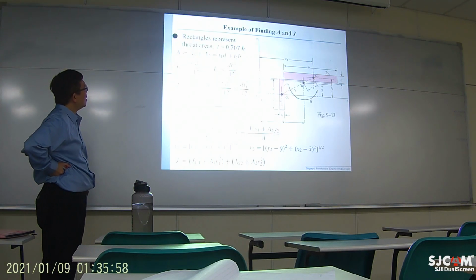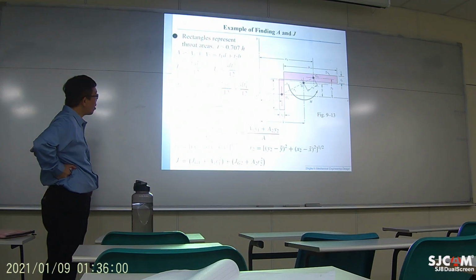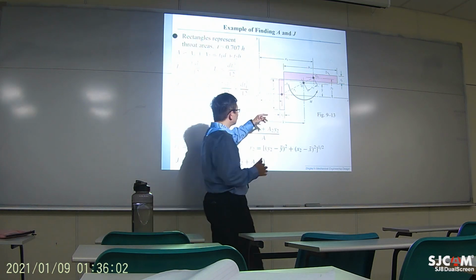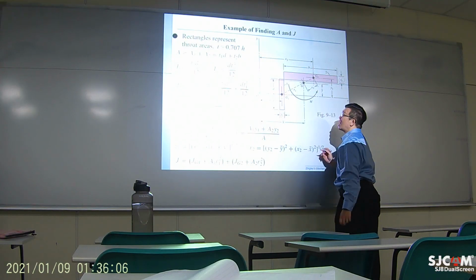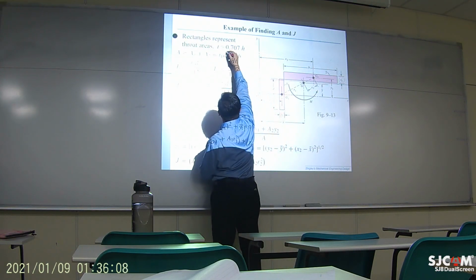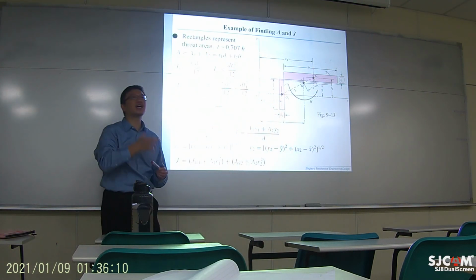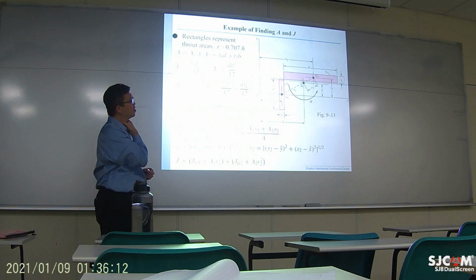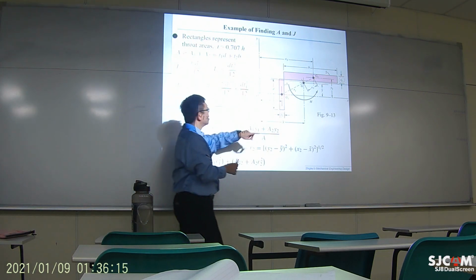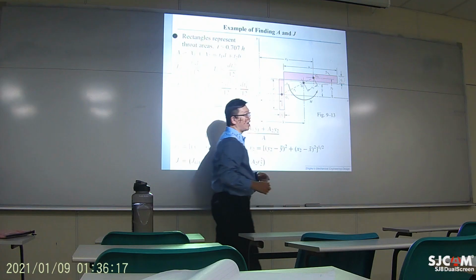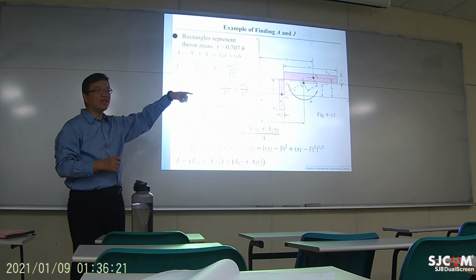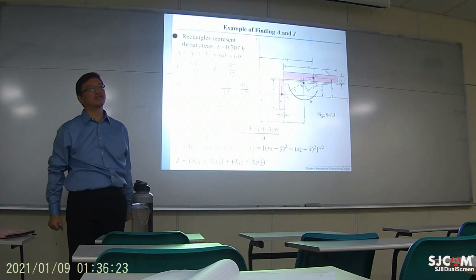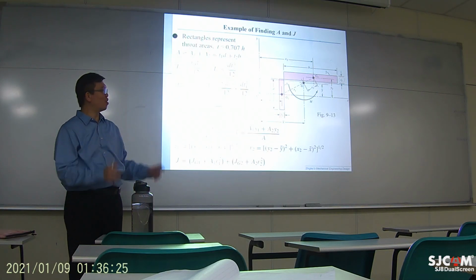Right here, whenever you make a drawing with the widths T1 and T2, it already considers the dimension of the throat. Okay, so this pink area represents the throat area inside the weld material.